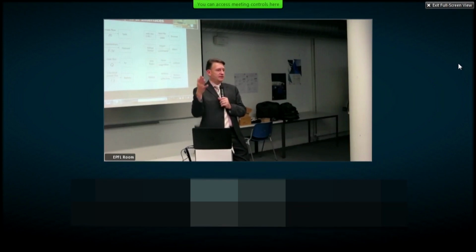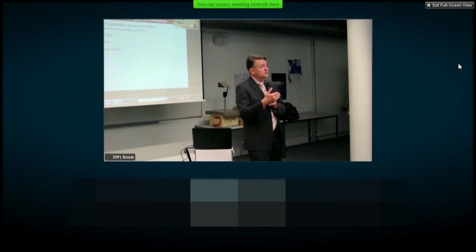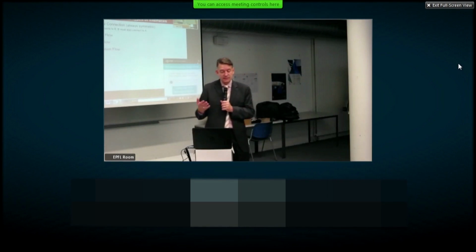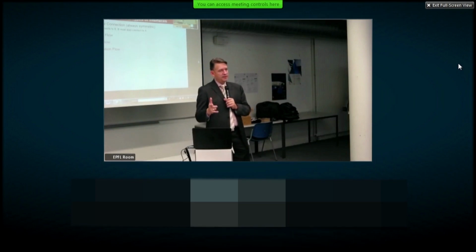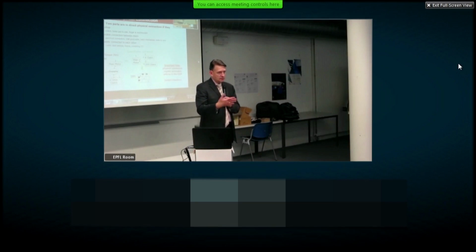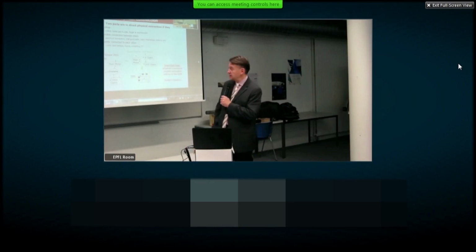And you can say, well, there are hundreds of types of interfaces. Well, no. The argument here is that all interfaces can be reduced to, or described by, these four canonical types. The first one is physical connection. So A connects to B, B connects to A. A physical connection typically implies that there's a force or torque that can be transmitted across the interface, and it's always symmetrical. And then we have energy, mass, and information flows. I'll give you some examples of each of these types of interfaces. These energy, mass, and information flows are typically asymmetric. They flow from one to the other. Physical connection is always symmetric. So let's go through these, and I'll give you examples, and then we'll see what we can do with it. So here are physical connection examples.